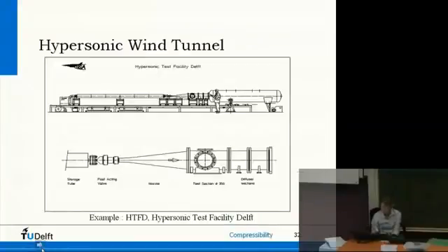This is our hypersonic test facility, which is a Ludwieg tube type. We have 2 small pressure vessels where we heat up the flow, because it expands and cools when it speeds up. We heat up the flow and put it under high pressure. And then we open the valve, which is down there. It goes through the tubes. Here's the test section where we perform the test.